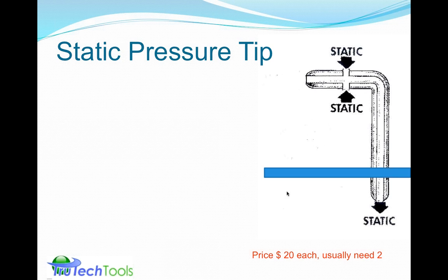What's it made of? Well, I look at a static pressure tip and I think of it as half of a pitot tube. Basically, the center section is sealed off, and all you have is one tube, and you just have the balloon pressure or the inflation pressure of the duct pressing on perpendicularly to the tube itself. So the static pressure tip is aimed into the airflow, and the static pressure is just the balloon pressure which is around, surrounding and inflating the duct.